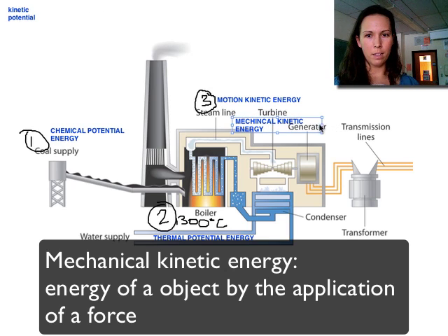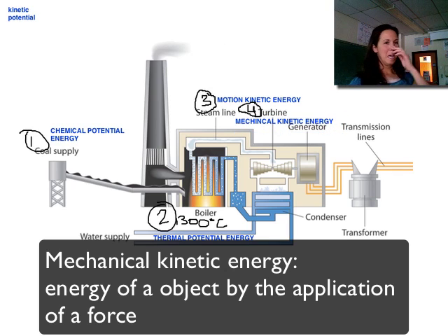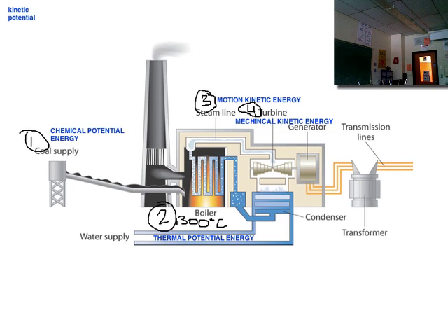Okay, and I'm going to label that as step 4 shortly. Just backtracking a little bit. Our coal gets ground into a little powder, gets shot into the boiler where it burns really, really hot at 1300 degrees Celsius, which heats the tubes of water. They're purified because if they're not purified, then that leads to corrosion and stuff like that, so they have to use purified water. Which then is kind of shot, I think they kind of bottleneck it, so it gets shot into these tubes up here.